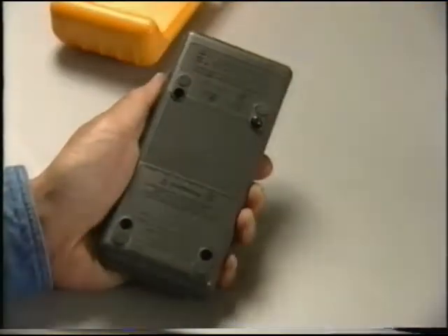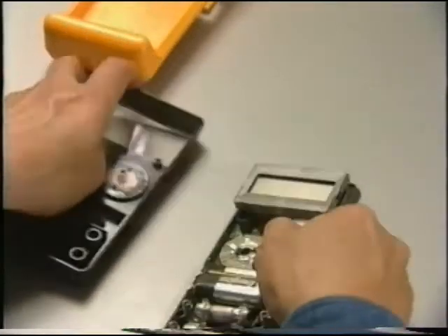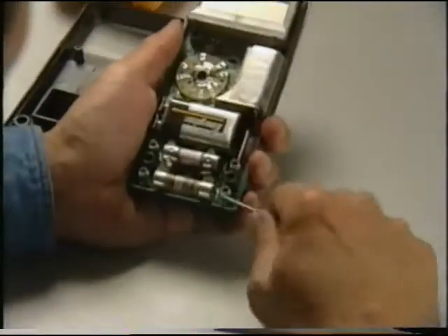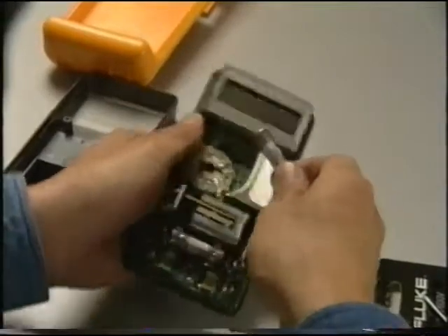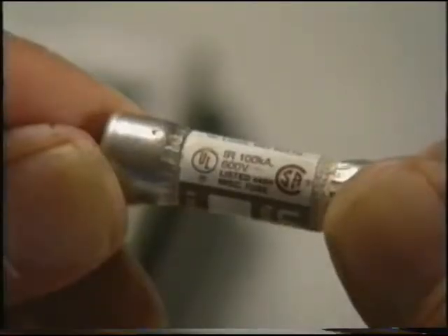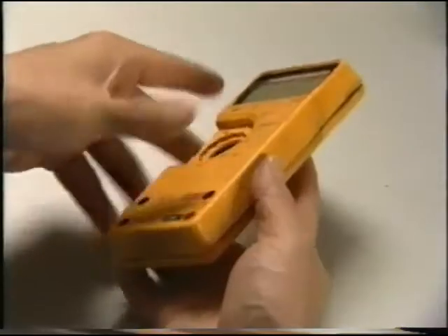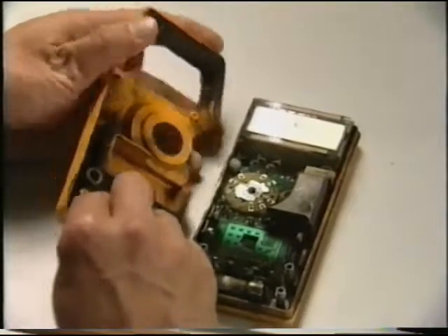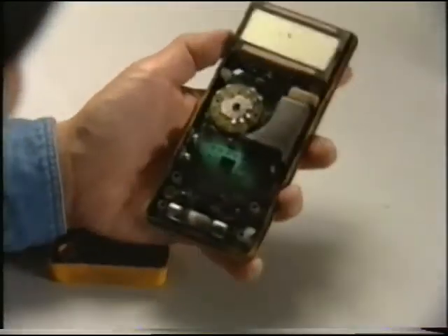If the meter is fused and fused correctly, the result will be a blown fuse, a small price to pay. Never replace a blown fuse with the wrong fuse. Only use high-energy fuses specified by the manufacturer. These fuses are rated at the same voltage as the meter, and some can interrupt fault currents as high as 100,000 amps. Here's a meter where the specified fuse was replaced with a low-energy automotive fuse. Fortunately, the meter took the brunt of the explosion, and the user escaped serious injury.